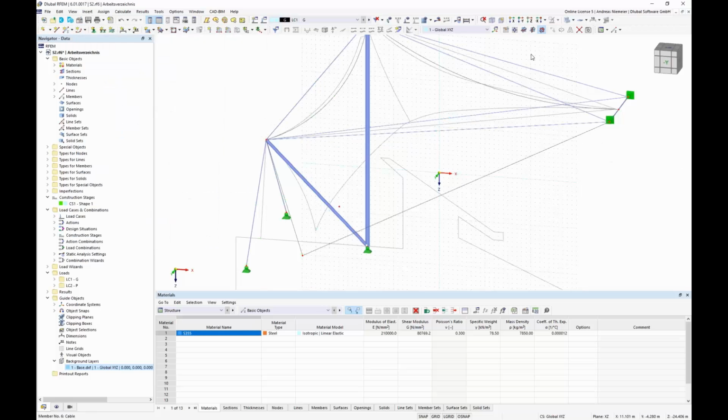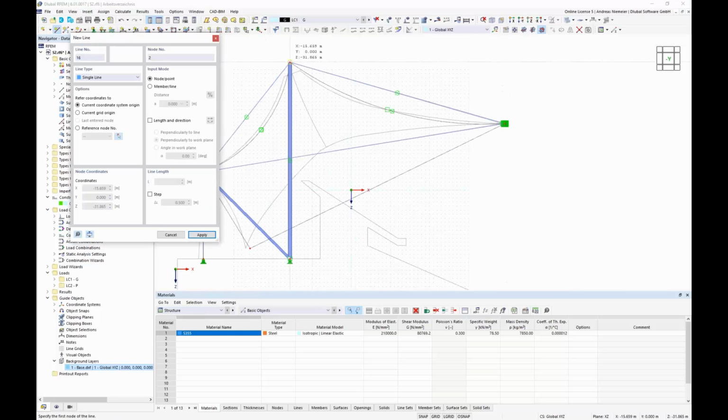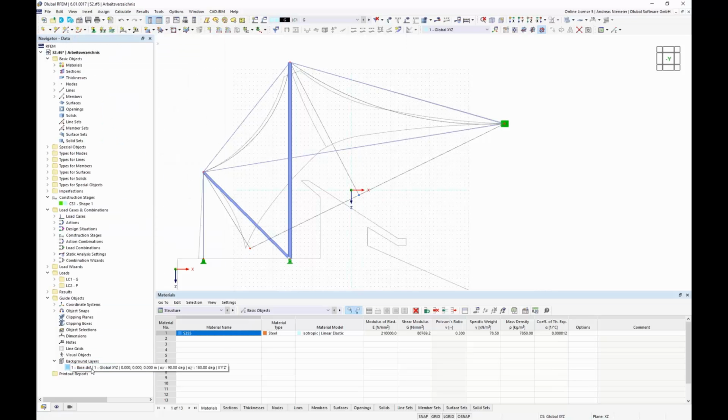Of course, it's not important if this line will match the DXF shape, because the form finding application itself will find the right place of structure. So it's not a target, it's only a, let's say, a tendency where it should go. And now we can, let's say, no, not completely, we need here a splice cable, so also define here a splice, and if we want to define it here on the perpendicular point, we can do like this. Now we can deactivate this shape.